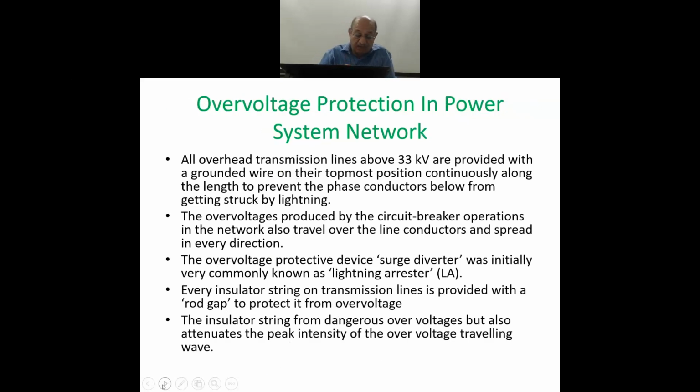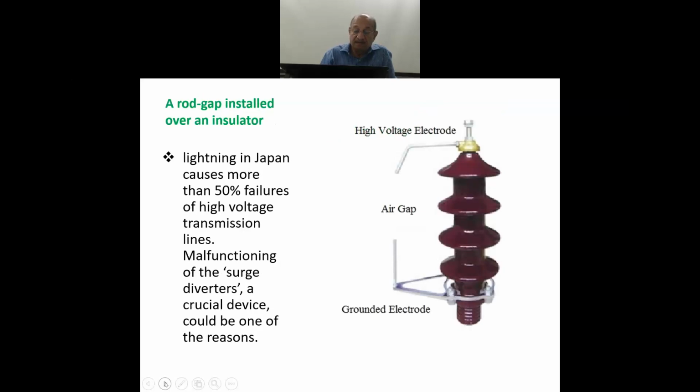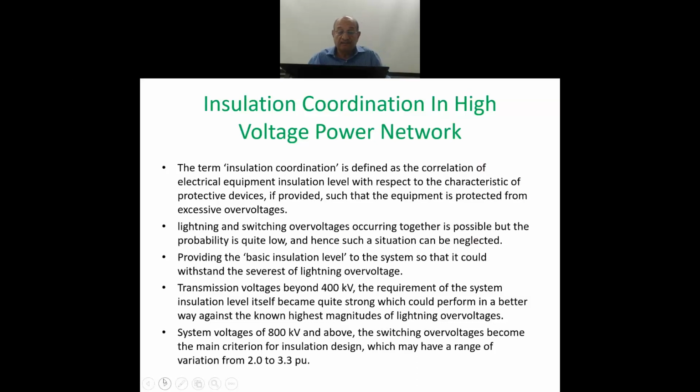Yeah, we do provide overvoltage protection systems in the network that we will be talking about in the later lectures. And insulation coordination is also provided to the system, so that we have just adequate insulation. We provide just adequate insulation, no over insulation and no under insulation.